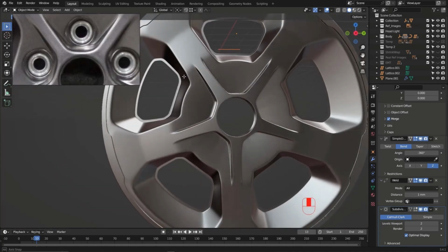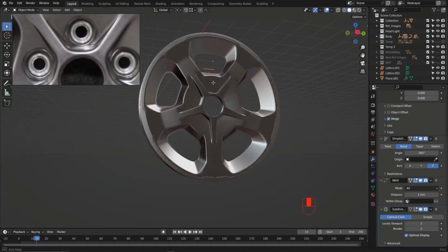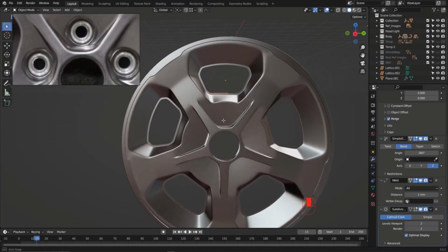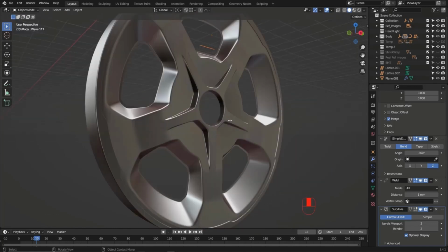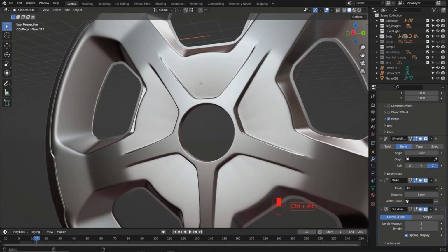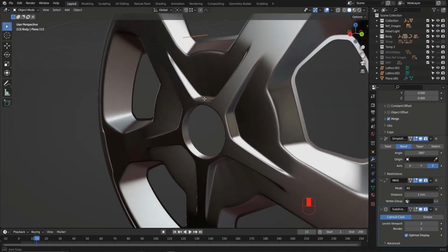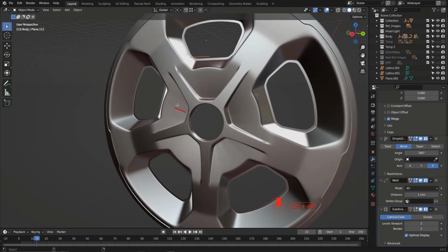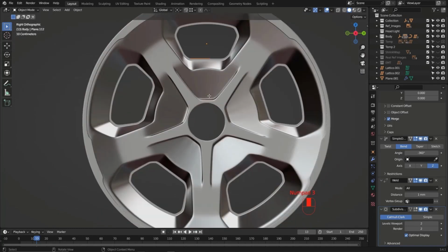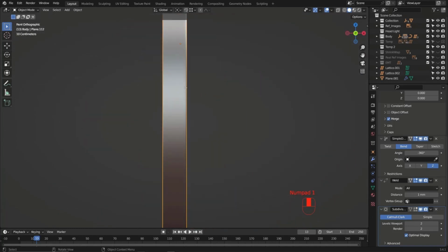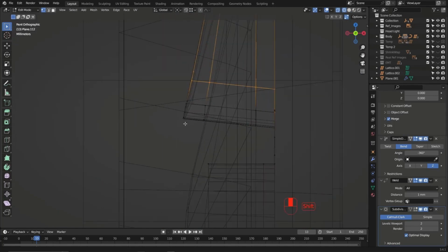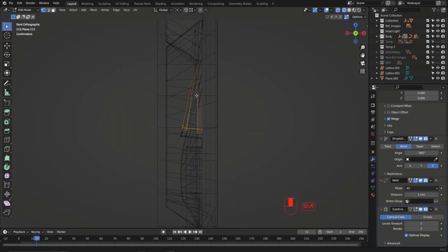Let's see if we could do anything else here. The result is very beautiful. I just want to get rid of this bad shading that we have right here. You can see or feel it here. Let's go to the right view, sorry, to the front I guess, and tab into edit mode, then go to wireframe. All we need to do is align these vertices, using maybe a guide.